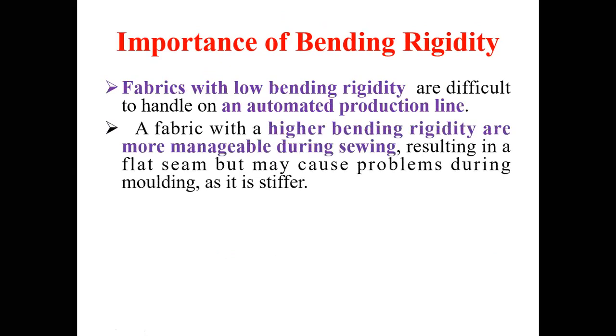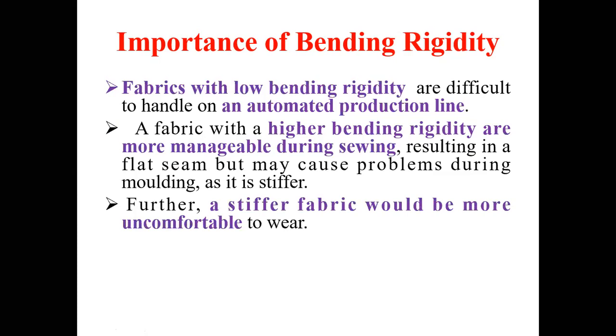Next, the fabrics with higher bending rigidity are more manageable during sewing. As I have already told you, if the fabrics are a bit stiffer, then you can easily handle the fabric. But if the fabric is very limp, then it is very difficult to manage during stitching. Now, this is one disadvantage of the bending rigidity. Stiffer fabric will be more uncomfortable during wear because it will restrict the motion of the different body parts. You can say like our hands, our legs, etc.